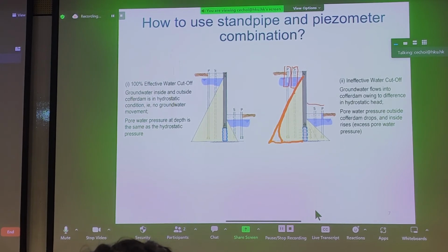And on the passive side, likewise, we have flow now moving into the passive side of excavation. We have standpipe and piezometer combinations. In this case, we see the opposite. It's not really a blockage, as in the reservoir case in the previous slide, except you might see in the piezometer an increase in the piezometric head relative to that in the standpipe. Standpipe still gives you a really nice indication of where the free surface is, but the piezometer will give you a localized pressure reading just at where the grout curtain should be.